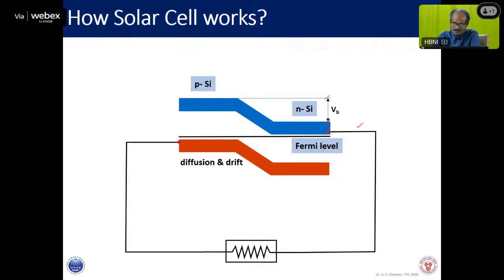In most of the cases, the diodes will be back to back, but not always. It will depend on the barrier, the work function of the metal and the electron affinity of the semiconductor, N-type semiconductor and P-type semiconductor. So what is the solution? Then in place of making a direct contact, people make the ohmic contact. There are different processes for making ohmic contacts.